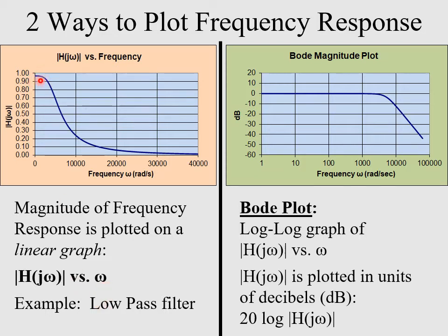You can see that at low frequencies, the magnitude is close to 1, so the filter is just going to pass basically any low frequency without affecting it at all. And then as we get to higher frequencies out here, you can see that this filter is going to block any signal coming in at these higher frequencies because its magnitude here is very small. It's a small fraction of 1, meaning that's what it's going to multiply the signal by. So it's effectively blocking it.